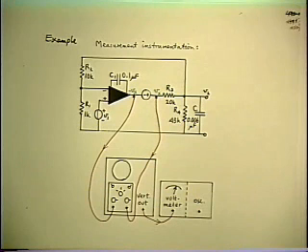In many cases, and again especially when we're dealing with switching power supplies, you have to be able to measure very small signals buried in a whole lot of noise. Because if you've ever dealt with a switching power supply, you know that its main output is noise. So you need to have some method of measuring a small signal down in the noise. And a narrowband voltmeter is certainly the first requirement to do that.